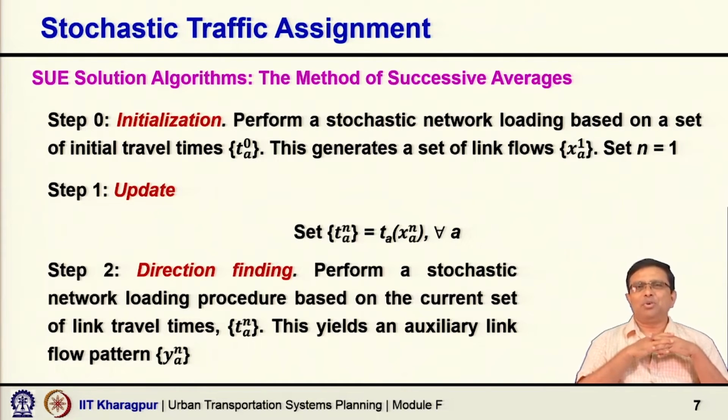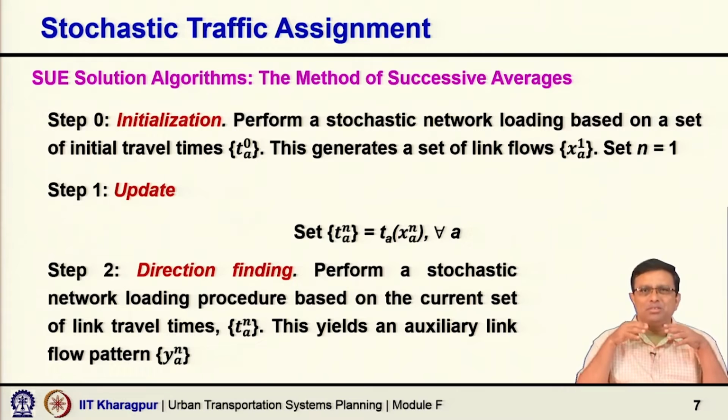Only the auxiliary flow, how we got there, we did deterministic assignment. So, with the current loading we got the revised travel time, and accordingly based on this revised travel time we then again assigned the flow, but the complete flow was assigned along the shortest path. And multiple times we did that. We updated the link flow and again started recalculating the travel time and accordingly load the network.